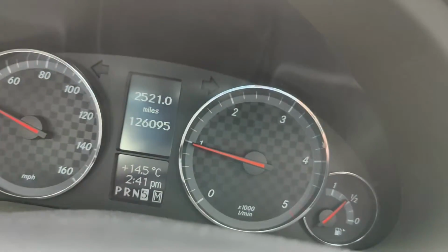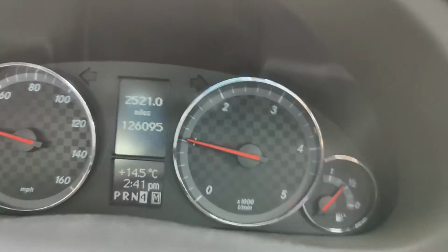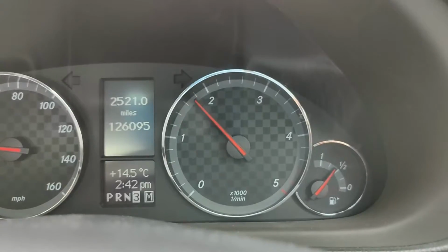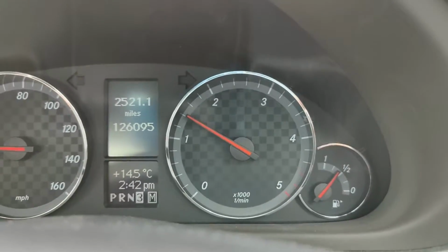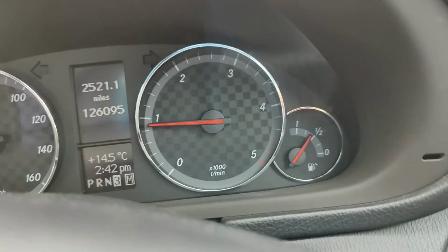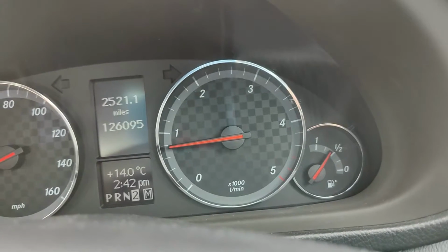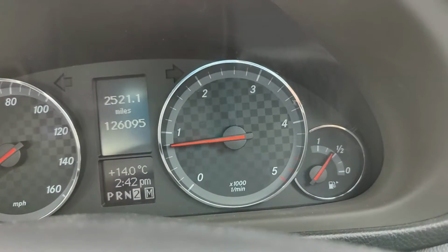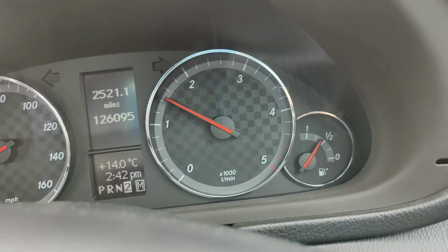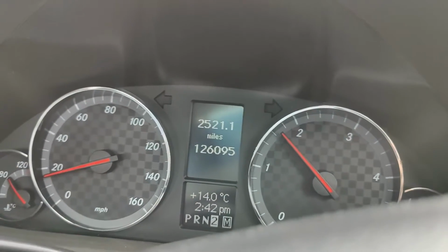This is impressive. Okay, back down to 4th. Okay. 3rd. Now the only thing I'm noticing is going back down to 2nd, it seems there's some drag on the gearbox, so I need to work out what's causing that. Here we go, there's 2nd. It's almost like the gearbox locks up for a bit. Huh. I guess we'll need to increase shift pressure there.